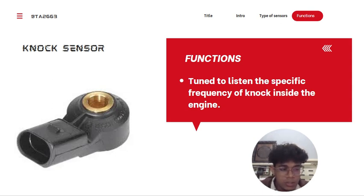If the knock sensor detects knock, it's going to relay this information to the ECU, and the ECU is going to respond by either retarding ignition timing or increasing the amount of fuel injected into the engine to prevent the knock from occurring again. In order to be capable of hearing the knock resonating through the engine block, the knock sensor is always going to be on the engine block. Many engines with 6 or more cylinders have 2 or even more knock sensors in some cases.